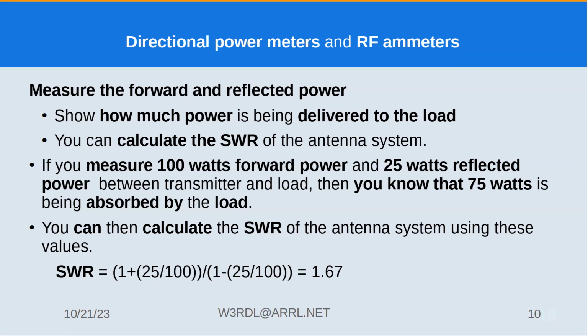But it's probably giving you a reading that's reasonable. It's not going to be reading true RMS, the cheap one. But if your house waveform is close to a pure sine wave, it'll be close. Generally speaking, it's the principle of you get what you pay for. And they're really, really cheap. Sometimes they're free. Well, $20, that's free nowadays.